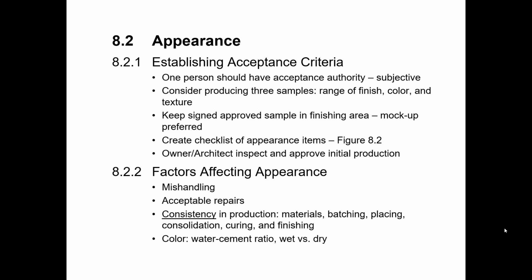Anytime there's veneer or any other special finish, make sure they understand what those things are going to look like. And then also the natural weathering. It's probably not a bad idea, if the owner or architect has never worked with precast before, to take them to a few different buildings that were produced from precast that are now 5, 10, 15 years old, and let them see how panels age and what they look like after a few years.